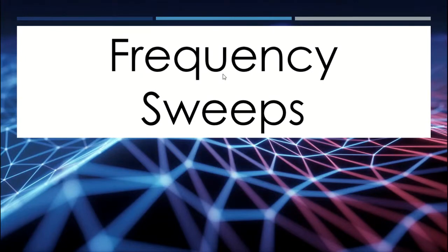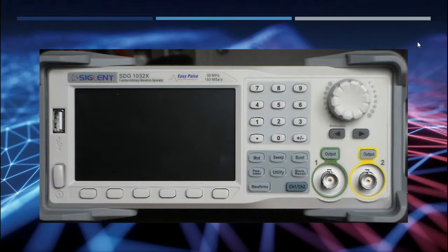All right, so again, the second type of waveform that we're going to be looking at is the frequency sweeps. In order to produce frequency sweeps, we're going to use that second button right there on the SDG 1032 Siglent waveform generator. So let's go ahead and take a look at the waveform generator actually producing frequency sweeps.